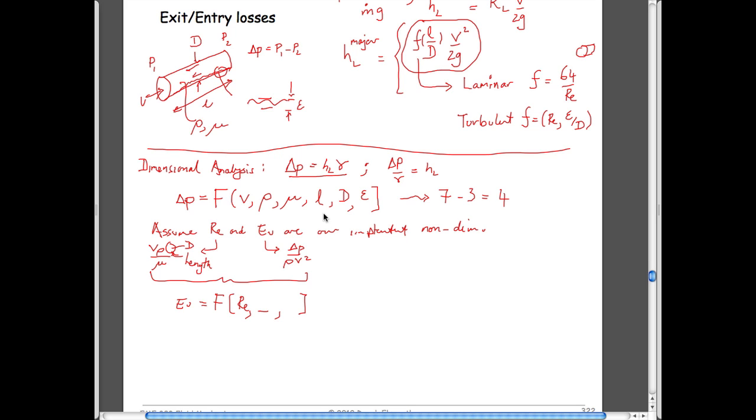And so certainly there are two other terms that could fit in here that would be non-dimensional if we're just doing them by inspection. You can do it by Buckingham Pi, or you can do it by inspection. We can take length over diameter, and we can take roughness over diameter, or length. Doesn't matter. It's just that I know the answer, and that's why I'm driving it. You could use any combination and do some experiments, and some of them would work out better than others as parameters, but you'd still use those same groups.